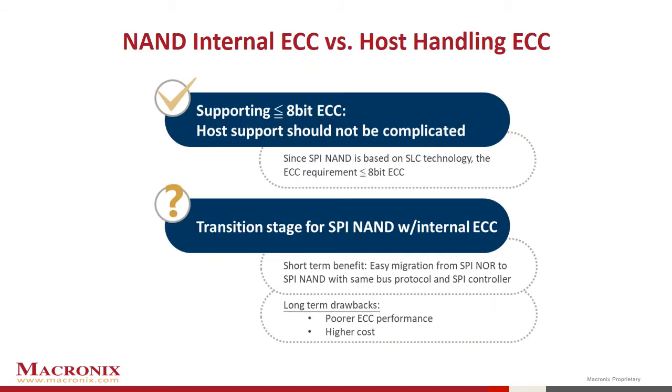In order to offload the ECC from the NAND, the host will have to implement the ECC engine. By doing this, the MCU will absorb some additional cost. A typical MCU may have approximately 3 million gates. A BCH 8-bit ECC engine requires approximately 50,000 gates to implement, which is an increase of roughly 1.7% in gate count. This die size impact on the MCU would be much smaller than the impact to the NAND IC if we were to add the ECC engine on the NAND.